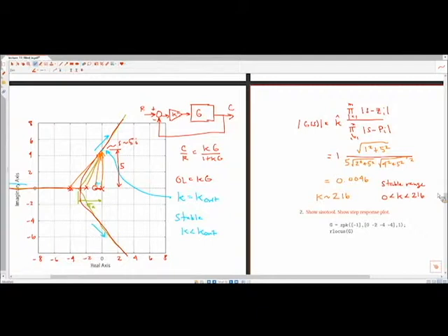So this tells us that we can increase our gain up to, say, 200, and the system still should be stable. This is, again, approximate, so we probably shouldn't push it to, like, 215 or something like that, because I just read this off the plot. This gives us a general idea of what range the system is going to be stable when we have feedback with a simple proportional controller.